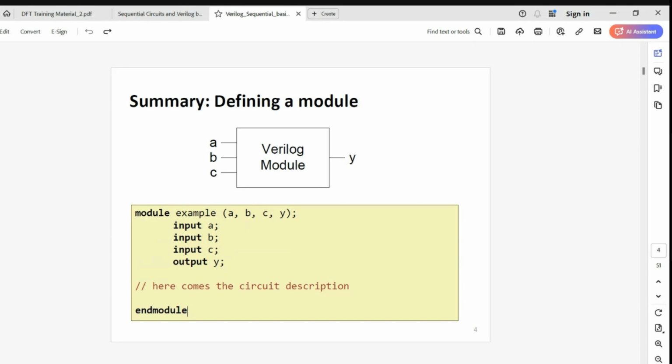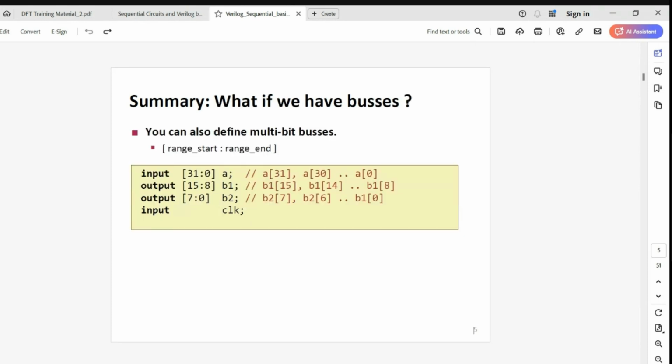Right. Next thing. In the previous image that you have seen, we haven't defined any data bus, the bit length of the port. Here we are defining it. Input [31:0] a means that the a port has a 32-bit length. So the data that you can give using the a port is up to 32 bits, like 101010, likewise up to 32 bits of data as the input.